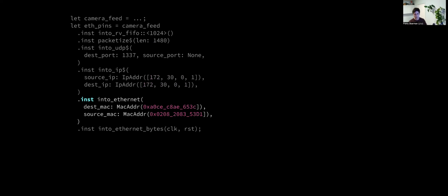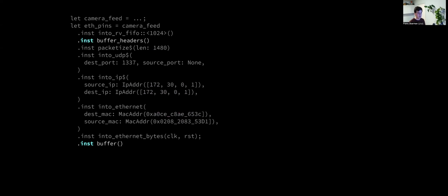Problem is, we're writing hardware, and we forgot that because we just chained a whole bunch of methods together. It's quite likely that the critical path will be somewhere in this method chain. Another advantage of doing this with methods is that the methods transform whatever the ready-valid stream carries, independently of what is underneath. So we can also have things that do hardware stuff like buffering.